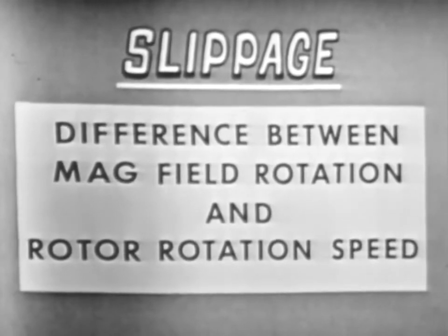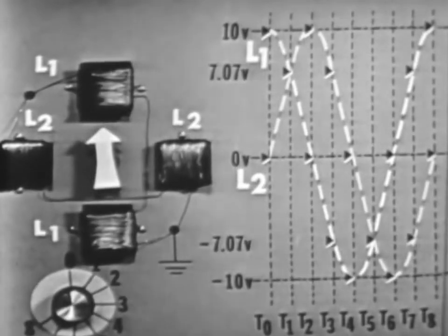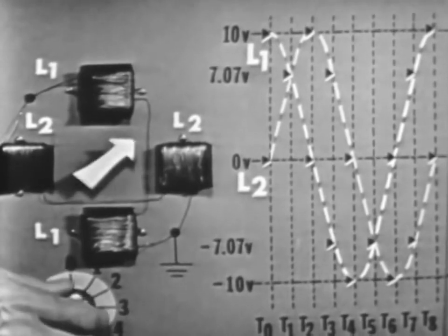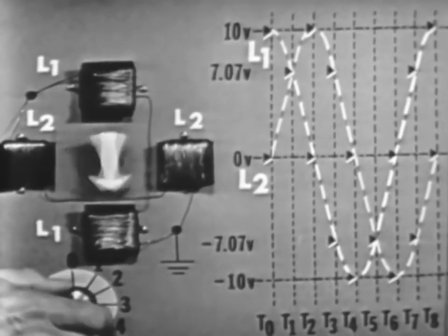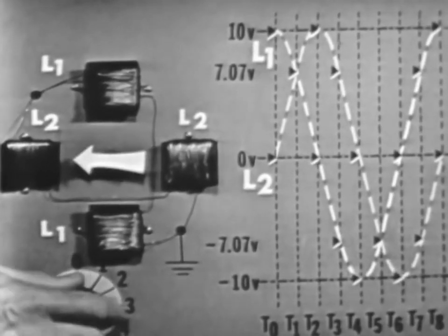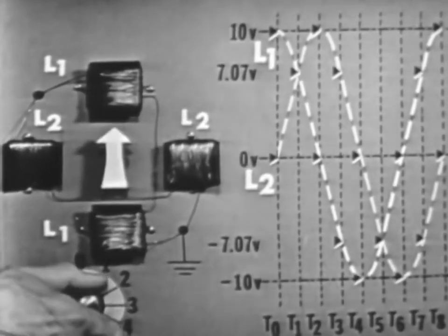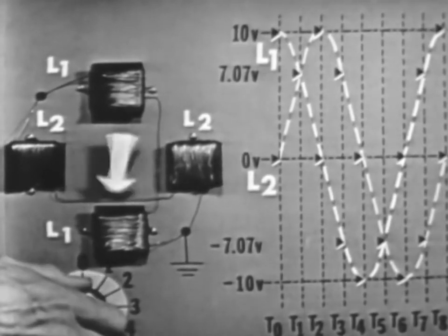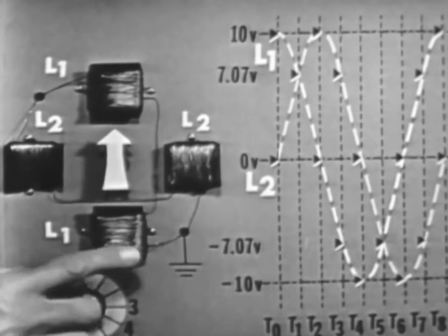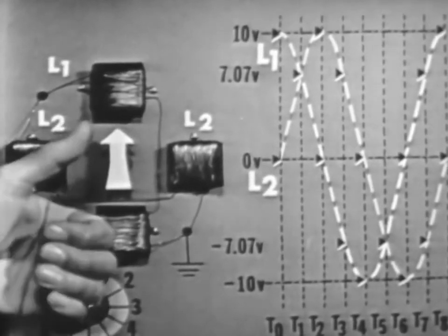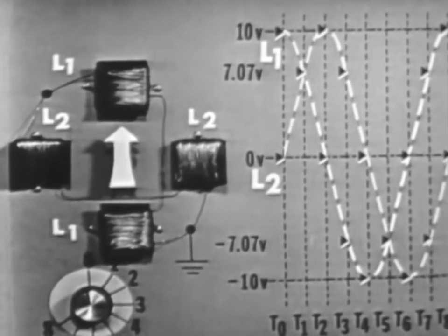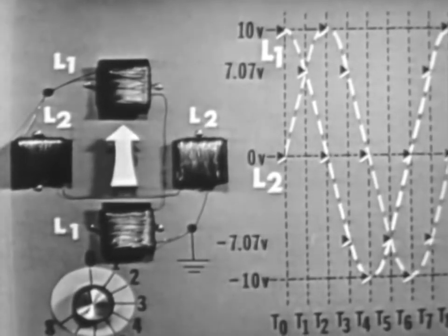Now, can I get item 7? All right, you can have it. Item 7 shows you how one complete revolution of the magnetic field is accomplished by applying these out-of-phase voltages to the stator windings. Now, you can study this very carefully so as to fix the principle in your mind. By the way, we might point out, Tom, once again, that you can apply the left-hand rule to all these coils and prove precisely what we've said, right? We can develop a rotating magnetic field.